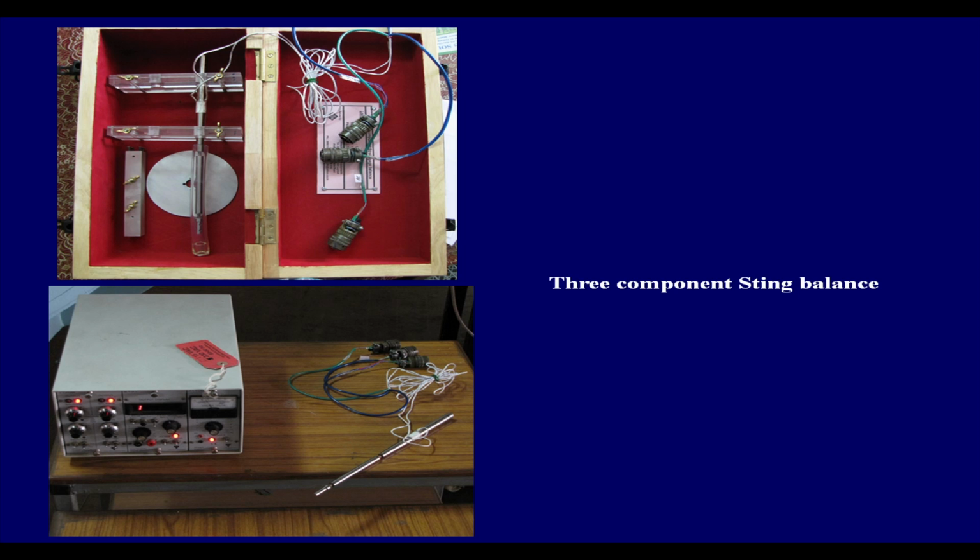The matrices should be available, the cross coupling and all that which you are aware of. Based on that, you know how the balance is expected to perform. Ideally, the coupling should be weak, but it never happens. Additionally, they have certain fixtures which can help you calibrate the balance from time to time. There are some utilities which we found good. They have also put some plastic covering and things like that, so the strain gauges don't get damaged due to handling problems.